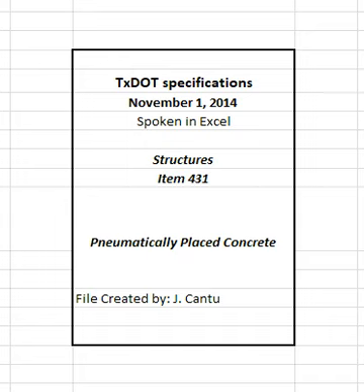Increase operating pressure approximately 5 psi for each additional 50 feet of hose and approximately 5 psi for each 25 feet the nozzle is raised. Table 2. Compressor capacities. See table in specifications. 3.4.3 Wet mix process. Operate the pump at a line pressure between 100 psi and 300 psi. Use delivery hoses between 1.5 inches and 3 inches in diameter. Use mixing equipment capable of thoroughly mixing the materials in sufficient quantity to maintain continuous placement.